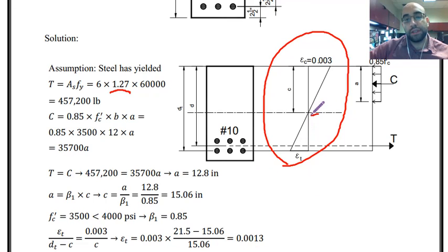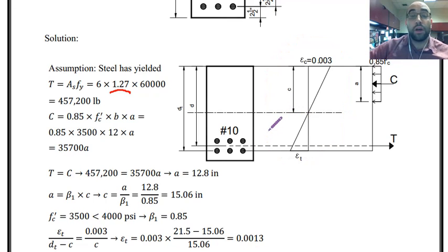Over here you can see this line is the neutral axis, and then based on the stage we can define a stress distribution. If the section that we are analyzing has cracked, we have one form of stress distribution. If it is not cracked, we have another form of stress distribution. And then the third stage was ultimate strength, which is the situation that we have over here.